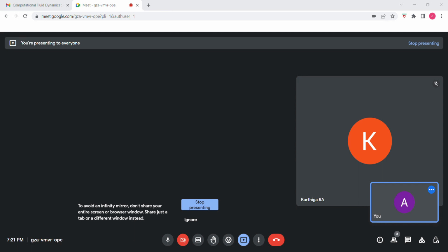They have asked the unit of Q. So K is watt per meter Kelvin, into Kelvin for T, by meter square for dx square, and putting all this together we'll get watt per meter cube.